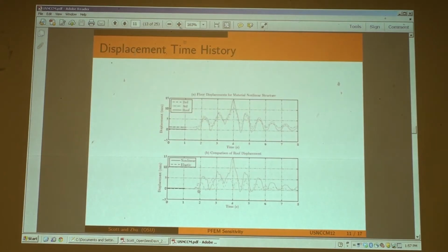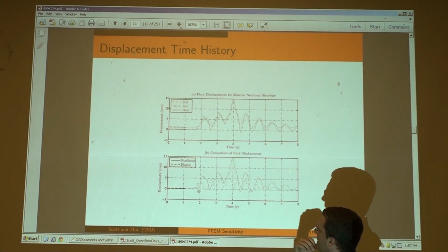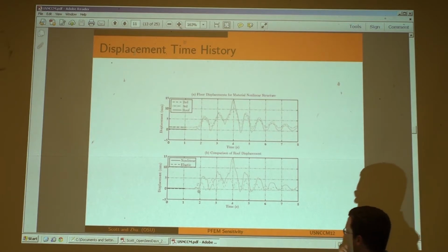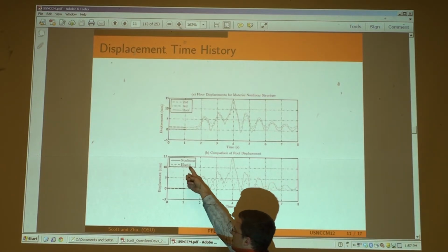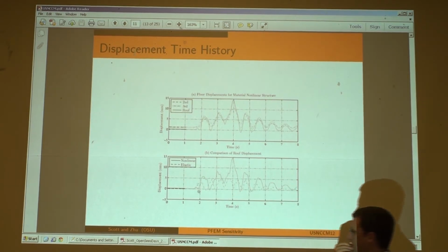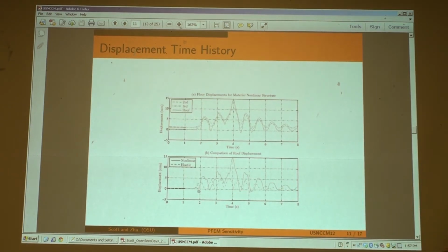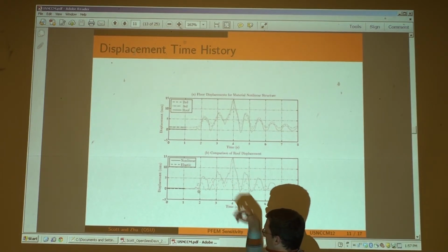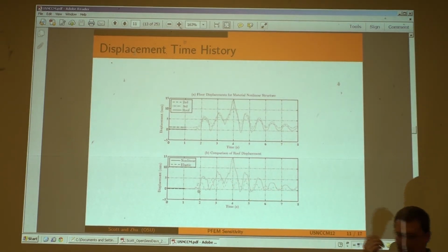And then we can plot time histories of the roof displacement, or the floor displacement. So up here is the second, third, and roof floors, all the time histories. And then comparing a linear elastic material behavior with nonlinear concrete 01, steel 01 type model. See, for the nonlinear materials, we get displacements about 3 times higher, which you would expect.